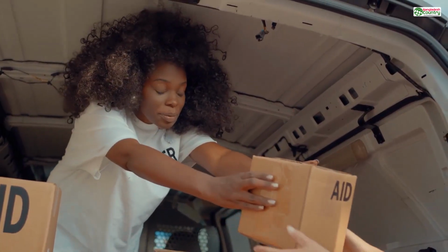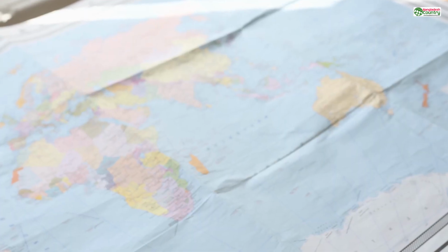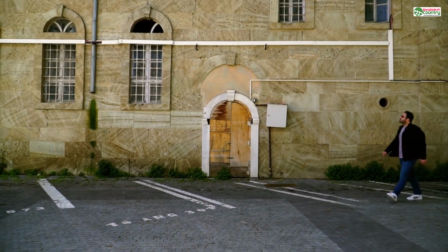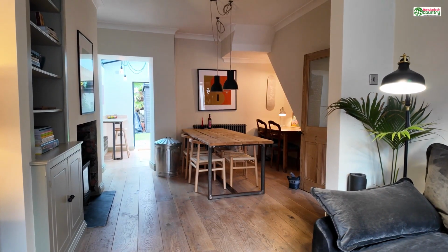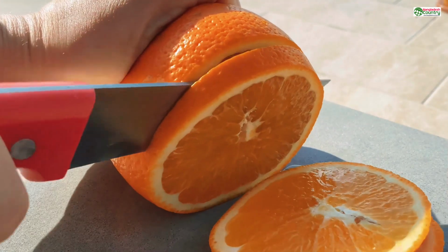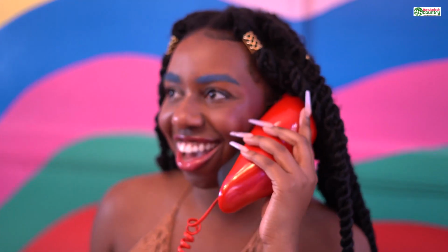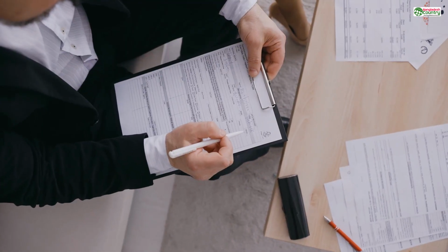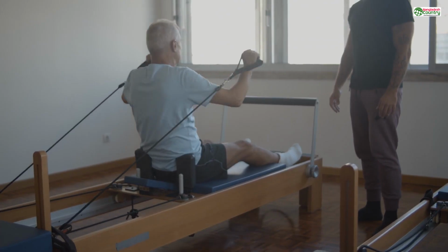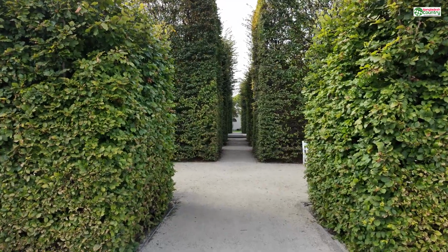Infill is the internal support structure of your 3D print. It's the secret skeleton. If you were to slice a 3D printed part in half, you wouldn't see a solid chunk of plastic. Instead, you'd see a pattern, a honeycomb, a grid, a complex web that fills the empty space. This internal lattice is what turns a hollow shell into a functional, robust part. And you, the designer, have almost complete control over it. This is one of the most powerful and often overlooked aspects of preparing a file for printing.